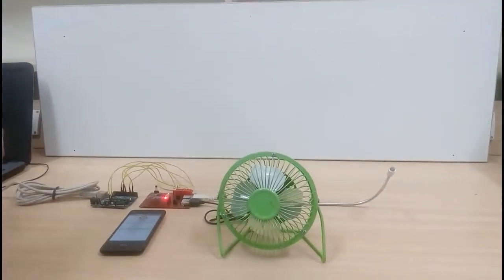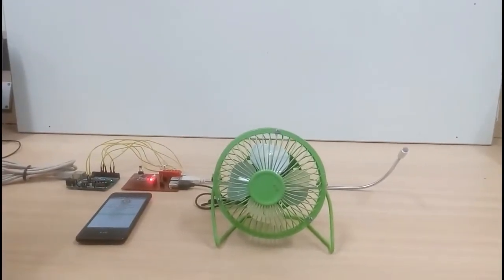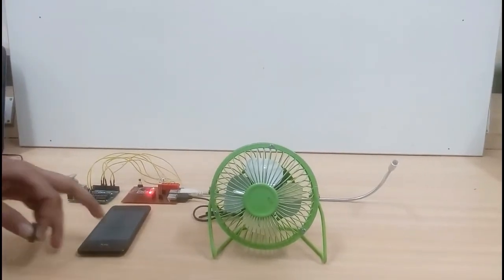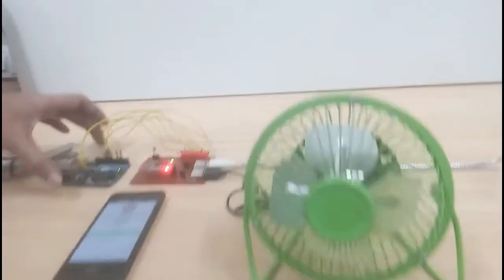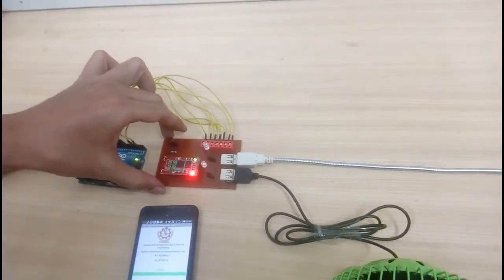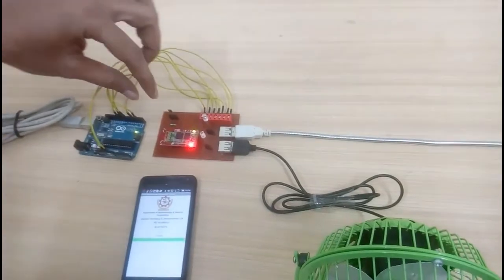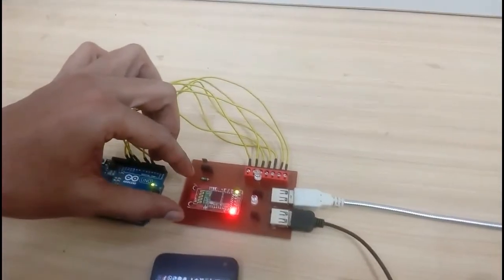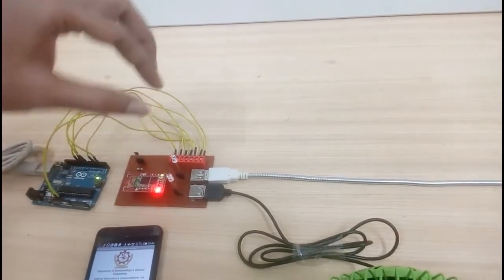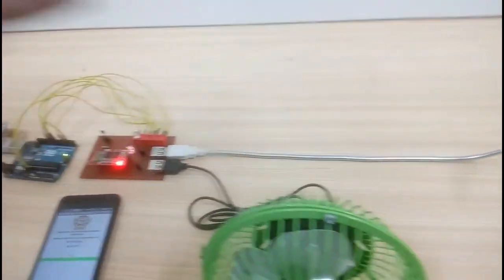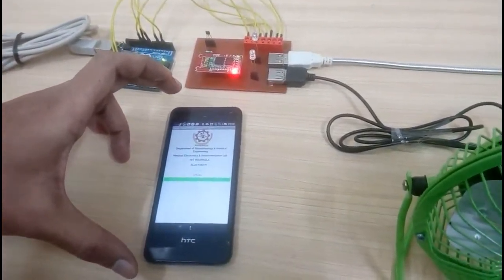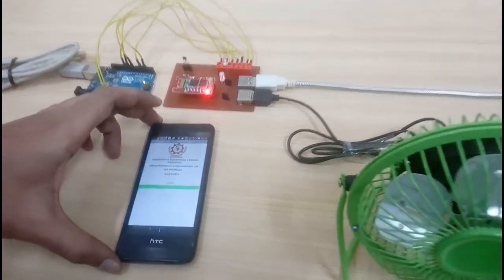This is a prototype voice controlled home automation system designed for locomotor disabled subjects. The system primarily consists of the Arduino board and its related program, the specifically designed printed circuit board, which mainly consists of the Hall effect sensor, the HC05 Bluetooth module, the interconnection ports, indicator LEDs, and the USB port for connecting the loads. It also consists of the Android app specifically designed for this application.